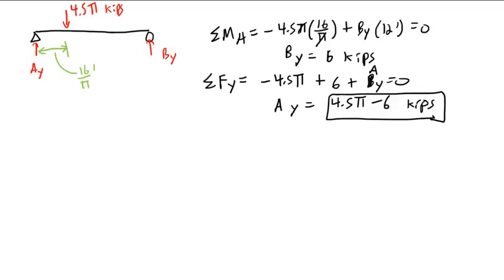Again, this is for the purpose, when can you use this? We have a beam subject. Yes, but what application of beam theory? Can you use it to find internal moments in shear? No, you cannot use this to find internal moments in shear. In order to do that, you still need to take cuts, and you still need to do it by inspection. So again, if I wanted to find the moment somewhere in the middle, I would still draw a parabolic load, do integration, etc., etc. All right, and that's it for centroids.